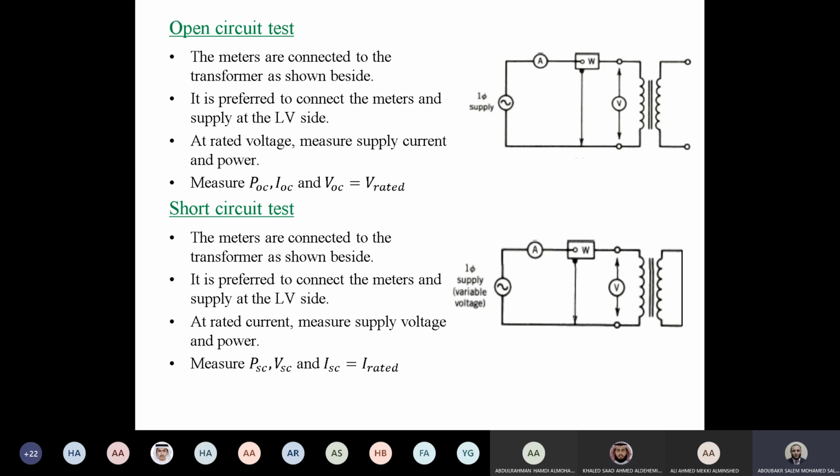Because we have some breakers at the panel that will trip if the current exceeds a certain limit. This is normal. Theoretically, the short circuit resistance is 0, so the current which is going to move in the short circuit will be infinity. Is it right? So in this case, we assume we will have very high current in the secondary side.